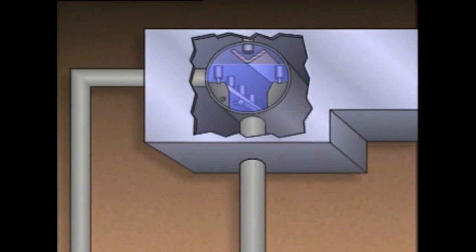In the opposite case, the boiler drum water level would rise. In a short time, this excess water would be carried out of the boiler drum, along with the steam, to where it could damage components such as the boiler's superheaters.